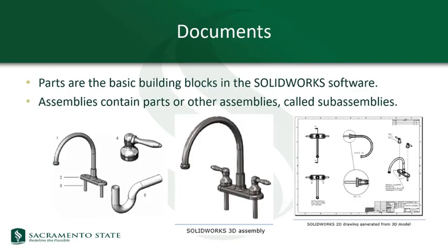There are two ways of building a product model. In the bottom-up approach, each component is first built, and then an assembly is made by combining the components. In the top-down approach, the components are created inside an assembly. Usually, a hybrid method is used where the initial design starts with an assembly and creates components in the assembly, but some components are also made as a part and inserted into the assembly. An assembly can also contain another assembly, that is a subassembly, that also can contain another subassembly, forming a hierarchy.